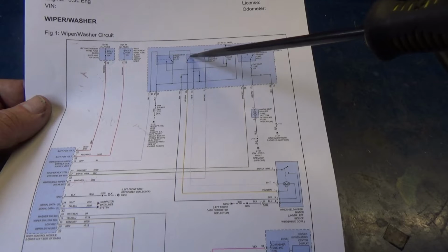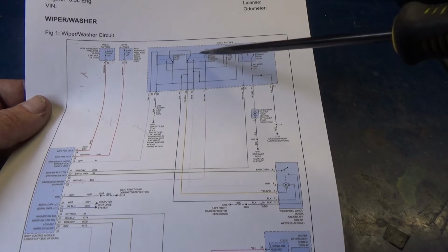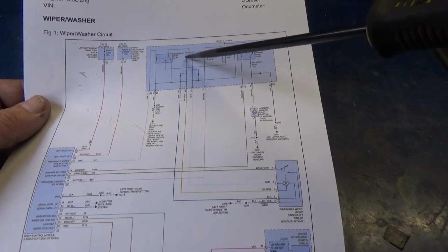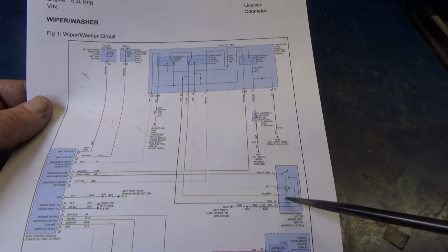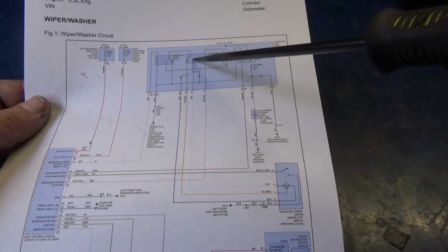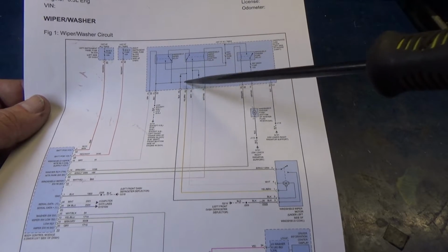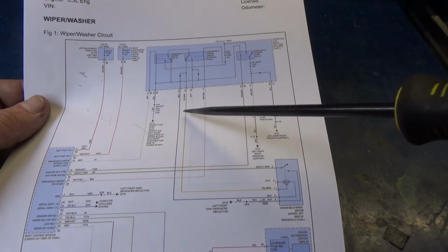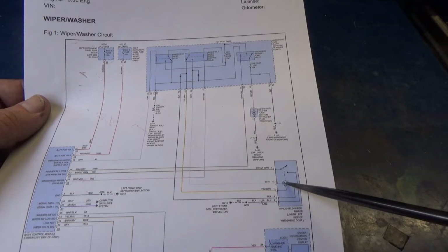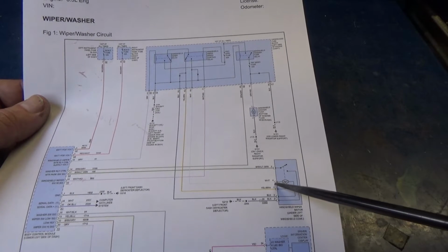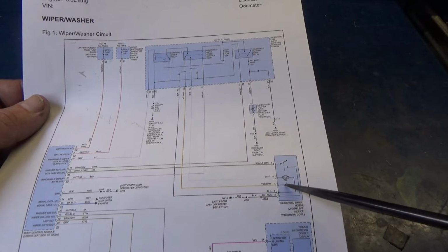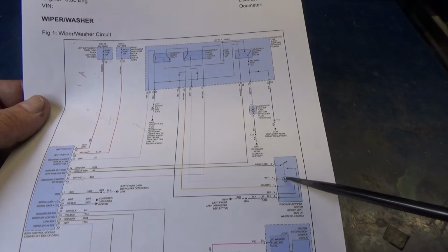Does that make sense? So when this high speed relay is relaxed, the on relay is sending 12 volts through this set of contacts down to the yellow wire to the low speed windings of the motor. If this relay goes over to these set of contacts, that means you just lost the 12 volts on this yellow wire. Which means that if the high speed windings of the motor was bad and you just lost the 12 volt on the low speed windings, the motor should actually stop.